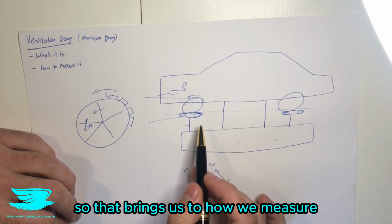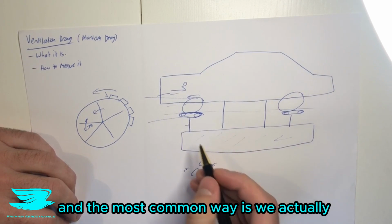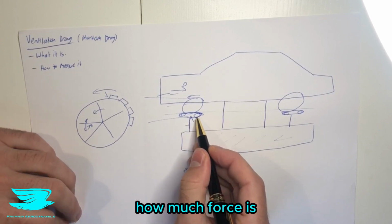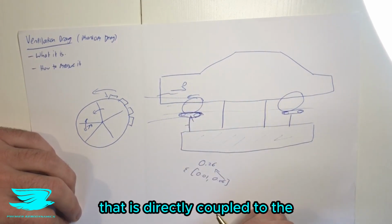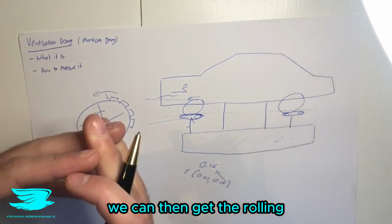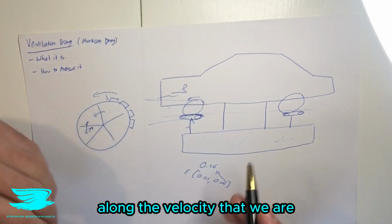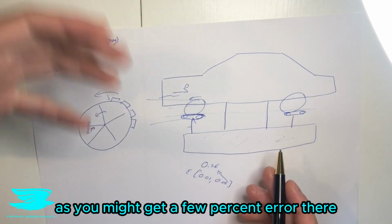So that brings us to how do we measure the ventilation drag? Well, there are two main ways, and the most common way is we actually put force, like load cells and force sensors in these wheel drive units to actually measure how much force is required to rotate these belts around. That is directly coupled to the wheel, the ventilation drag, as well as the rolling resistance. We can then get the rolling resistance out of that by running the car at a very low velocity and assuming that the rolling resistance is constant along the velocity that we are driving along. That is an assumption, yes, but it is a pretty decent assumption. We might get a few percent error there.